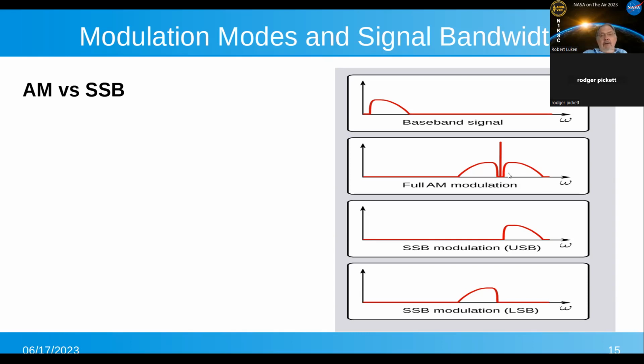So you get a frequency shift of a plus and a minus against the carrier. Now for single sideband, they use filtering techniques to eliminate the carrier and one of the sidebands. So when you transmit upper sideband, you just see this part. So you still have 100 watts in this instead of 100 watts spread over all of that. Likewise, lower sideband is the lower one.